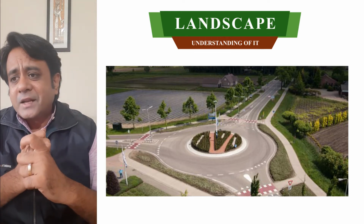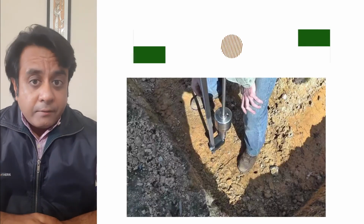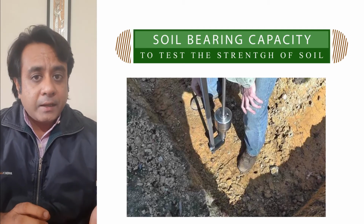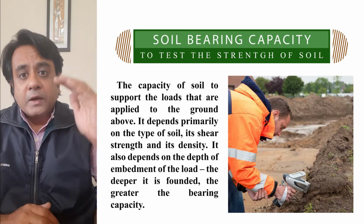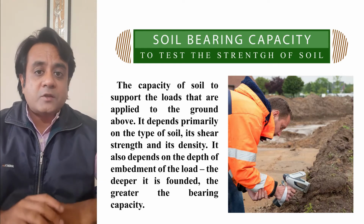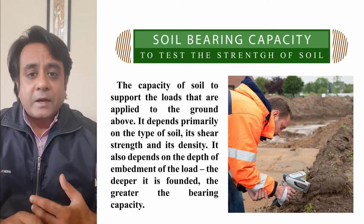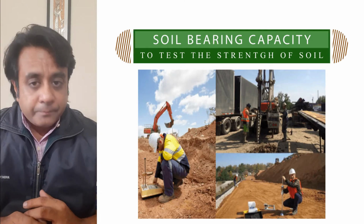Then you need to understand the soil bearing capacity, which is very, very important, because unless you do that, you will not be able to take a call on how high the building can go, or what load it can take. Sometimes the building is not very high, but the purpose is such that even on fewer floors, the load calculation has to be very strong. Let's say it's a godown, or a factory, or a press, or something like that, so you need to really know the soil bearing capacity.